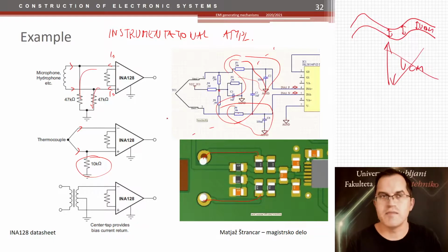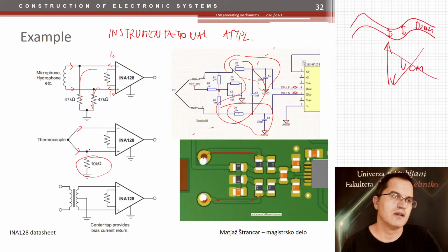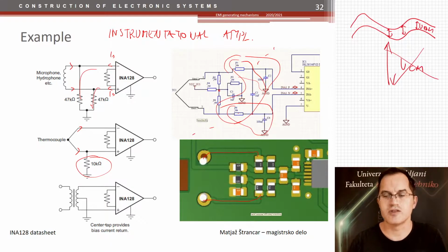And that's how he made sure that any common mode noise that might couple into this thermocouple would be equally taken away on each side of the input of the amplifier, and therefore the differential voltage noise will not build up.